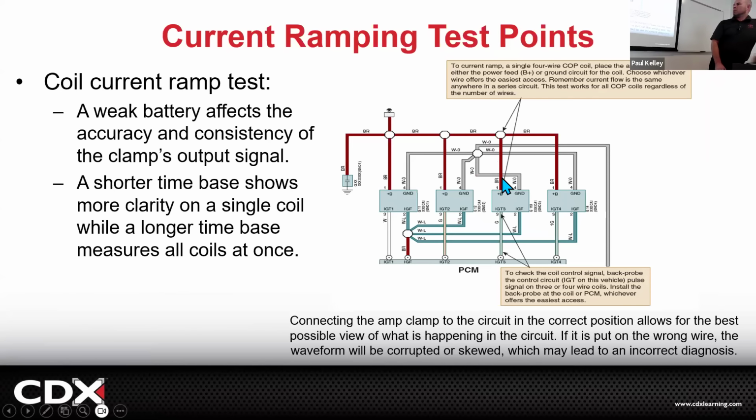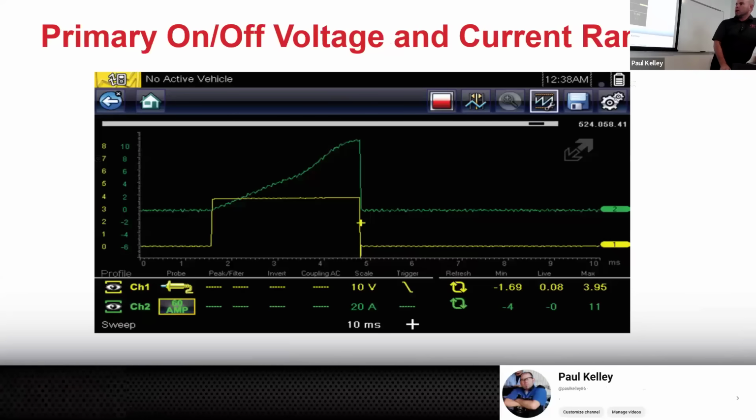We're going to be poking generally for the positive for amperage, and generally for the negative, but not the negative for the coil on plug, but the actual trigger that the ECM provides. Make sense? Very good. And then this is actually a really cool function.